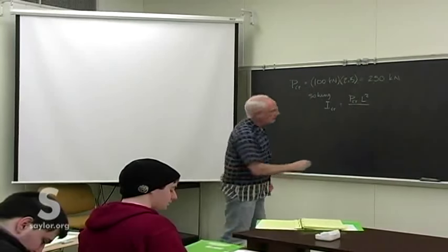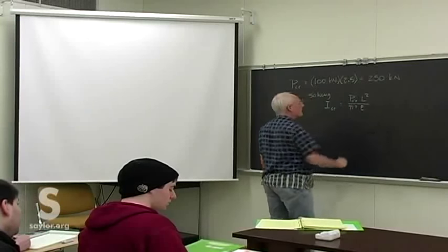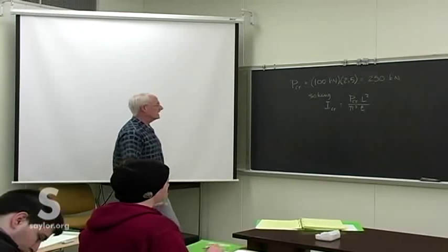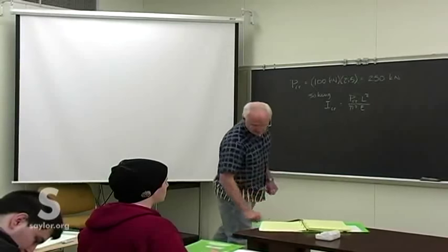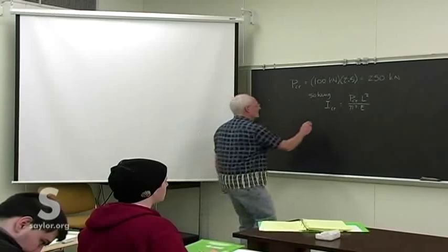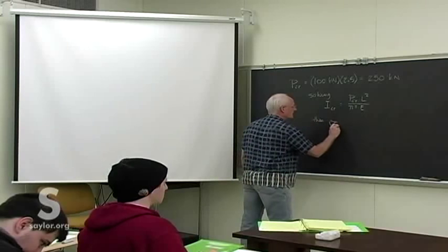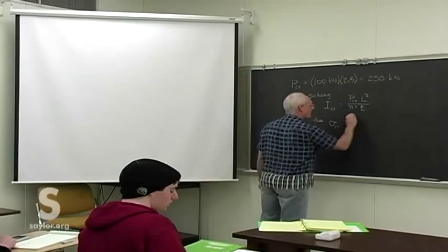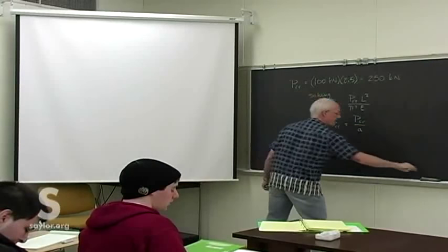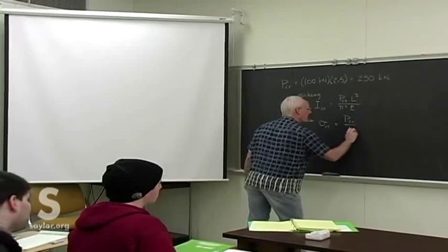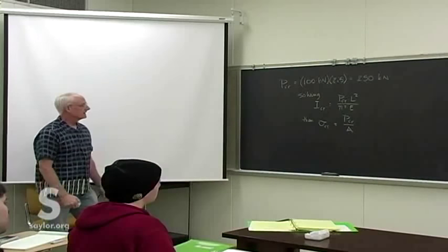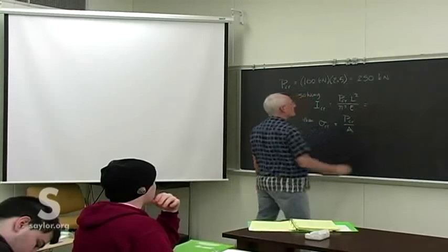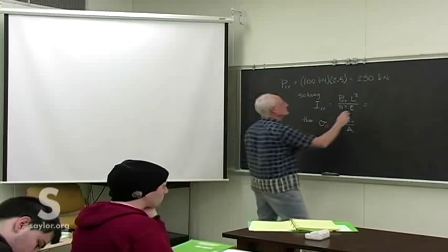And all of the pieces then are in there, pi squared E. That'll give us a critical area and allow us to solve then for A. And then once we've got that, we check that against the allowable stress that was given, and determine if it is below that limit. So most of the work's done. All we have to do is watch our units as usual.